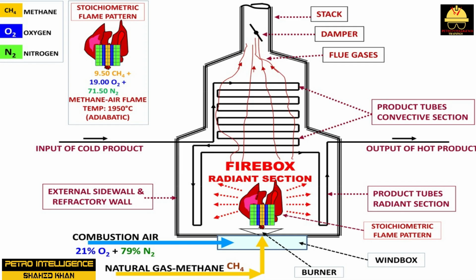When the East Pass tube enters the firebox, it receives radiant heat directly from the burners. The West Pass tube enters the opposite side of the firebox and also receives heat from the burners. A bridge wall may separate the two passes in the furnace. As the charge, that is, process flow, leaves the furnace, the passes, tubes, enter a common header and are pumped to the processing unit.